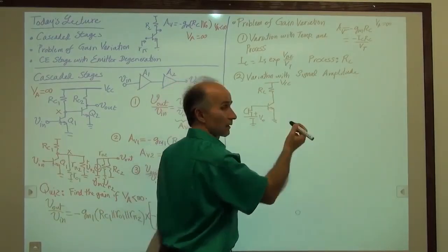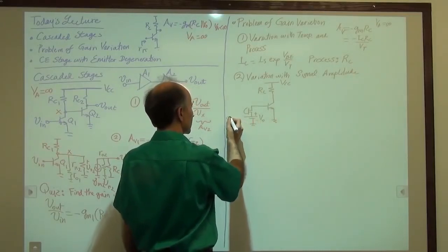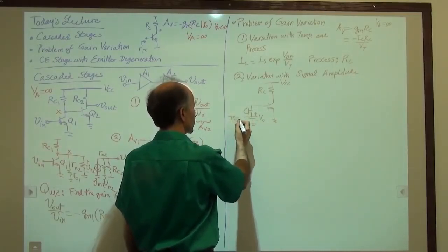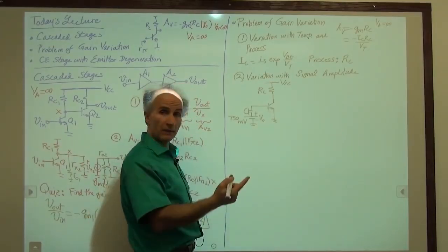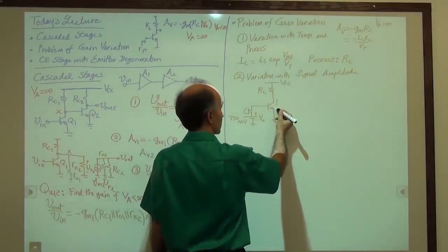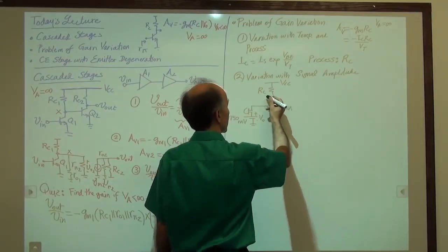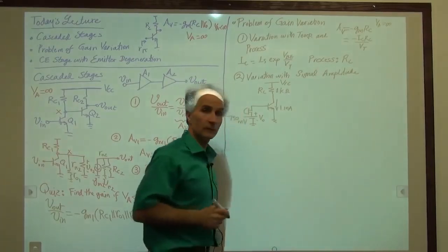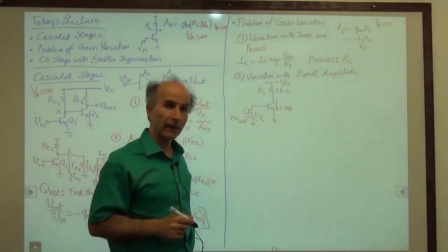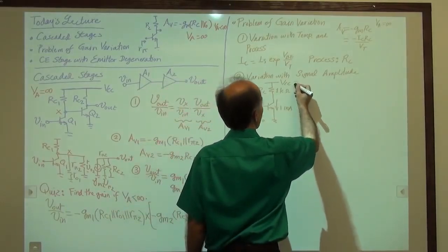And again, let's pick some examples. Suppose this is 750 millivolts, V0. That's the base emitter bias voltage. That gives us a collector current of 1 milliamp. For example, I choose RC to be 1 kilo ohm. Okay? And I will choose VCC to be 5 volts.